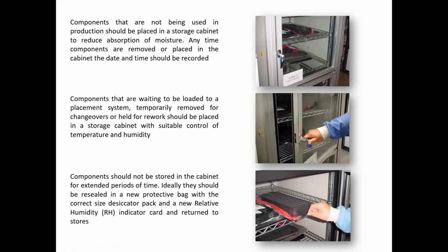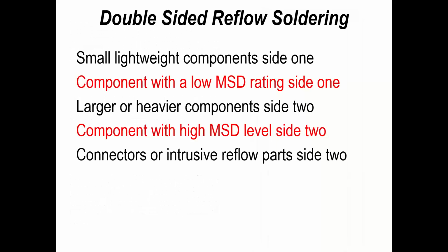An alternative to protecting boards and components, which is more popular today because it reduces the amount of handling that is sometimes necessary in manufacture, is lockers and ovens, humidity ovens, to protect the components and the conditions they're stored in. So again, there's lots out there, and you follow the procedures. On some systems, you've got automatic monitoring of how many times the door is open, what the moisture level is like, etc. All these tools are out there, basically to protect the boards and components from what we possibly do to them in manufacture.